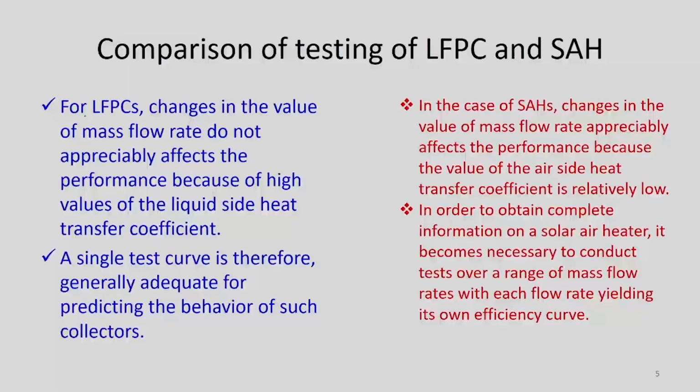If we compare both liquid flat plate collector and solar air heater, in case of liquid flat plate collectors, changes in the value of mass flow rate do not appreciably affect the performance because of high values of liquid side heat transfer coefficient.